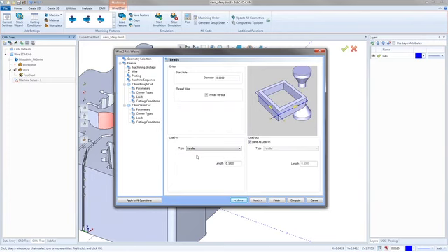So I'm going to say, let's do a parallel here, because I actually want it to start off the part, come in, make this cut, and leave. For parallel, I don't know how much extra I need. I don't know what size this fillet is, but I'm going to give it a 1/4 inch extra. Hopefully that's enough. If we need to, we can always add a little bit more.